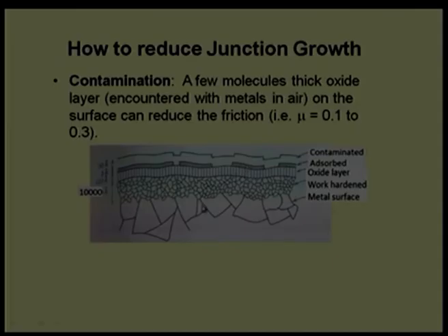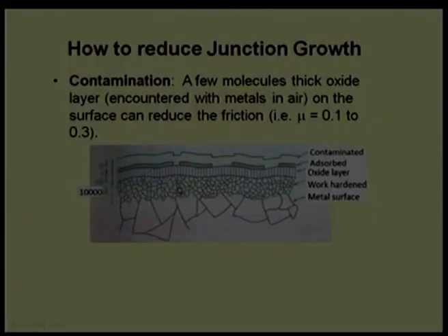However, in steel and chromium, we can get a good number of layers, good oxide layers on top of the surface, and they prevent adhesion. They make the interface a weak shear interface, or the shear strength of the interface is almost negligible in those cases. That is why we get a low coefficient of friction. However, if we remove these layers, the coefficient of friction will increase.